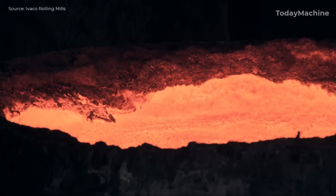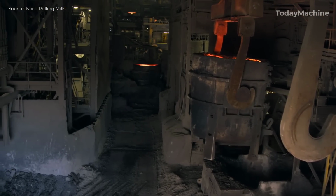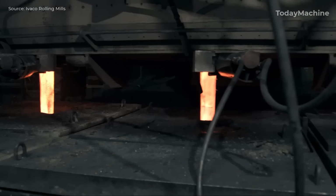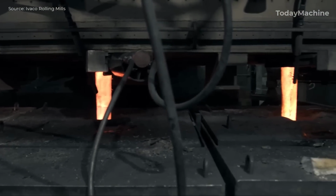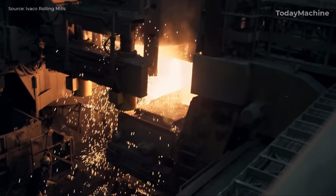Refining and continuous casting. Once the scrap has melted into liquid steel, it is tapped from the furnace into a ladle, holding 78 tons of molten steel. The ladle is then moved to the ladle metallurgy furnace, LMF, where the steel's chemistry is refined and adjusted.